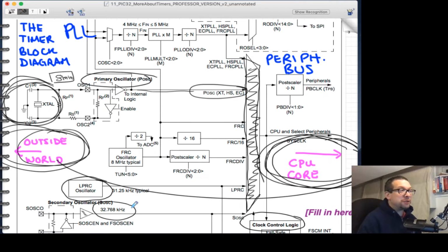These are useful for any timing related or clocking related task that syncs up with regular human time. Whereas when we use these 8 megahertz, 4 megahertz, 16 megahertz crystals, that doesn't really come into account, because we can't hit exactly 1 second or 1 millisecond.